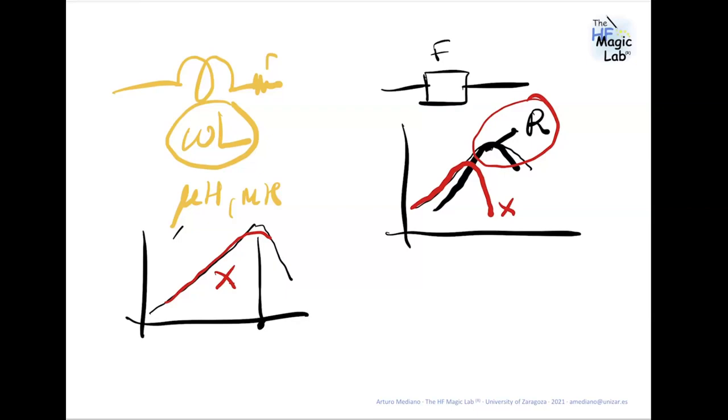Should I put some elements or traces below the inductor or the transformer? No, never. Below the transformer or the inductor, the best option is to put a ground plane as close as possible. Yes, you can change the value of the inductance and introduce some losses, but in my experience this is not a very big effect. It's more important to contain the energy in the area of the inductor, not spreading it around the system. Remember that in EMI, the best answer is "it depends", but let me say never.